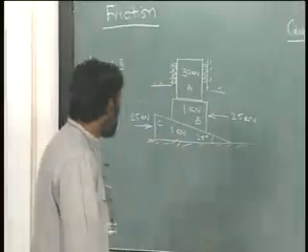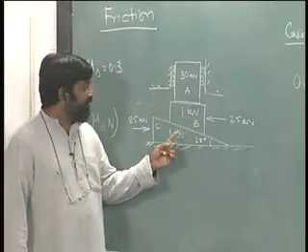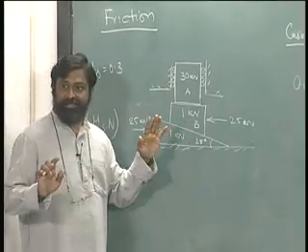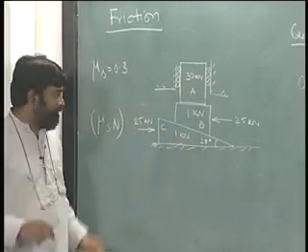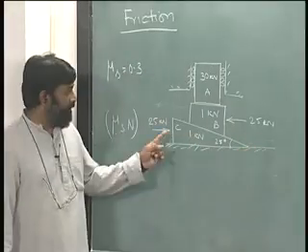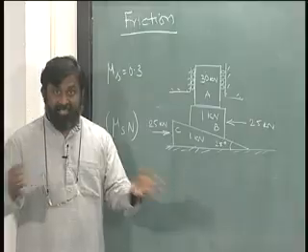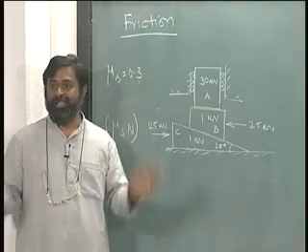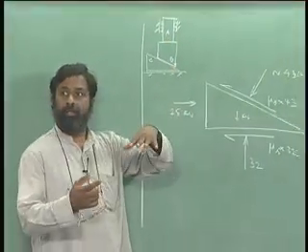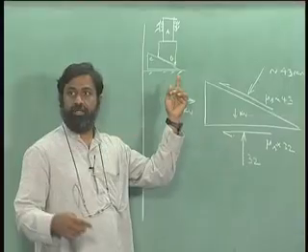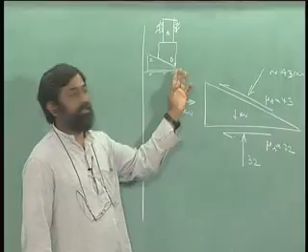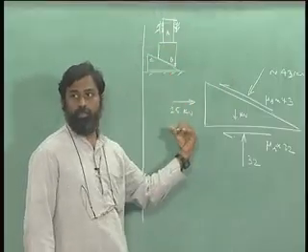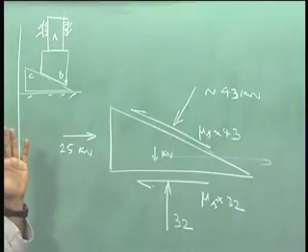So far so good. So one of the good things that we have seen is that this guy is in stationary condition, this and this together are now occurring. There is one possibility of pushing this, okay. If I look at that possibility and discount that, then I know the entire thing is in static equilibrium. Okay, we have seen that A and B do not move relative to each other because of the earlier exercise that we did. Now let us see if only wedge C can move towards the right, in which case it can go up. There is an up or a down possibility, okay. So let us look at those possibilities.